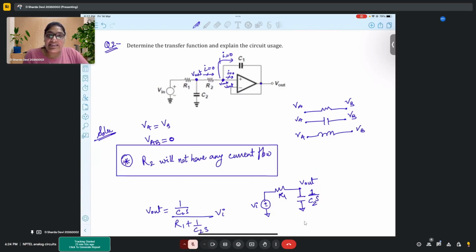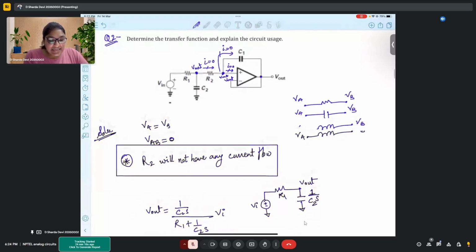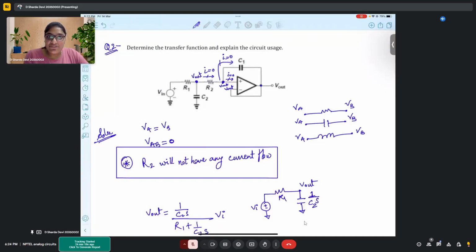What happened is it is just making your circuit bulkier, so it occupies more space on your board, be it a PCB board or an IC design. But at the end, the functionality that the circuit is performing is that of a first order low pass filter, right? Actually, this type of circuit you would observe with a slight change, and that we call Sallen-Key topology. It is used for higher order low pass filter circuits, but there is a slight error in the placement of components because of which we see this behavior.